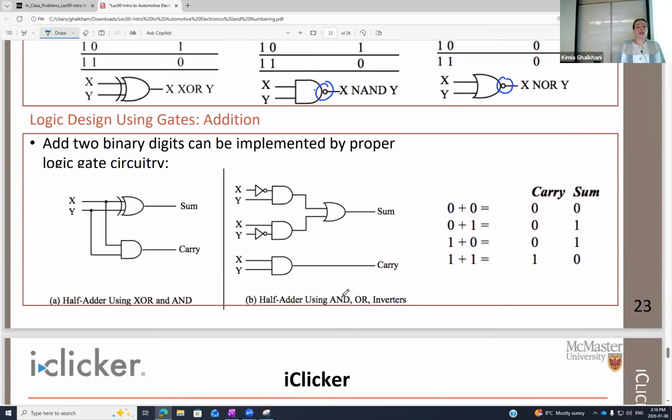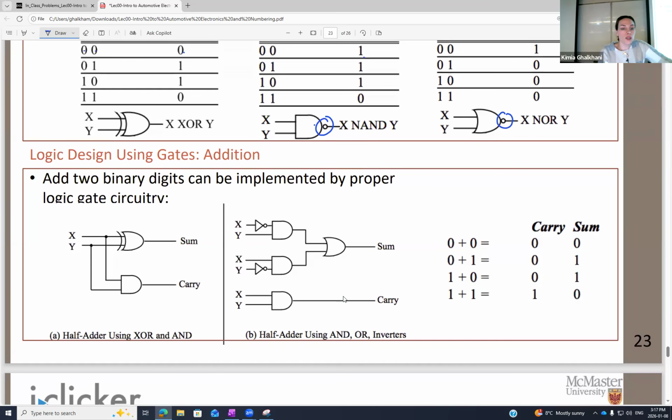We can do some logic gates summation. We can add them together. We can add, for example, NOT to AND and so on to create summation. Something like that. If I have something like this, we already know this is XOR, right? I just learned it in here. So I know this is XOR. If I have an XOR in here, and an AND in here, and I'm having the same input for both of them, it's going to be called a half adder. It's a half adder because I have a sum in here and I have a carry in here.